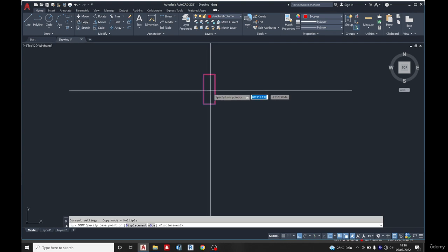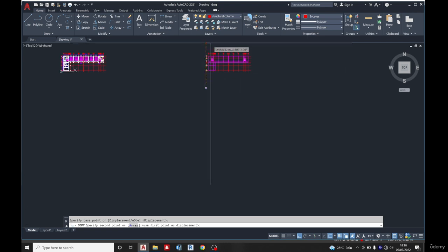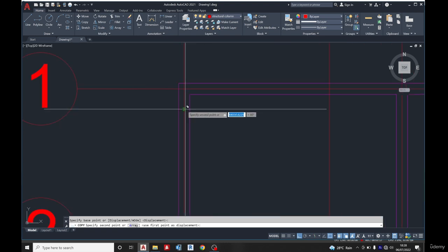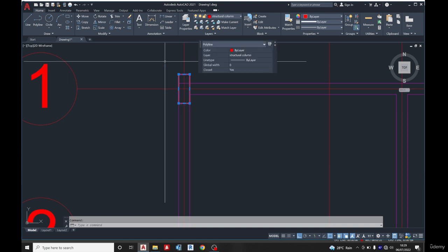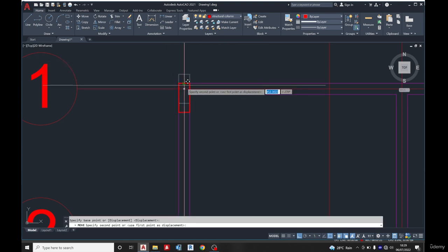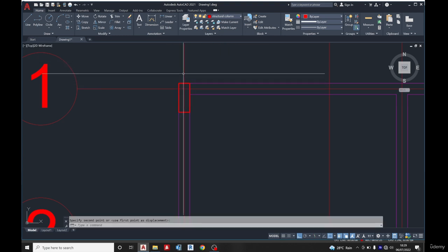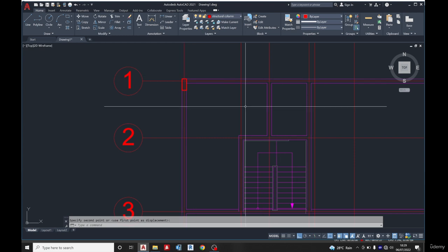Now, placing your column, you are going to place your column in the direction of where moment is maximum. So for example, I have this column. So if I'm placing it and I decide to place it at this point, let me shift this inside so it gives an eccentric column, which we'll be modeling on the softwares we are going to use for analysis.